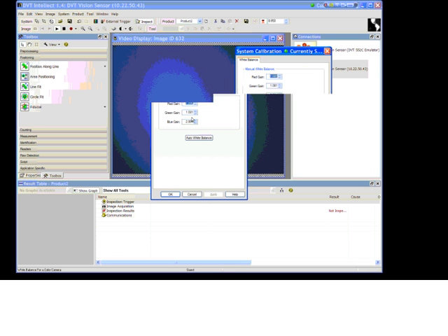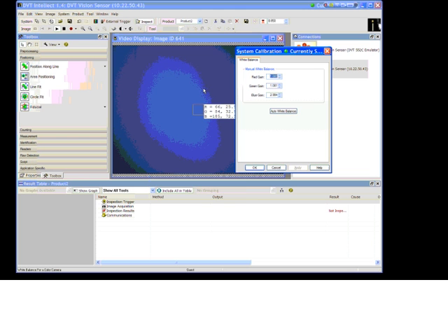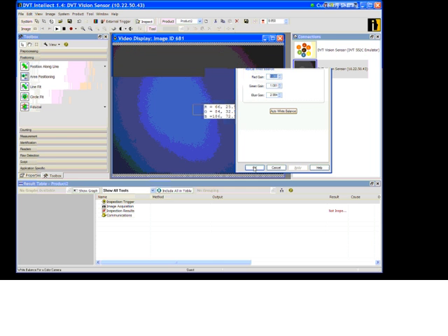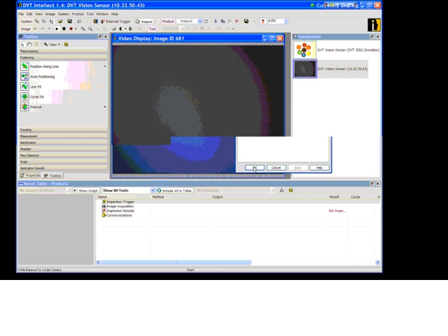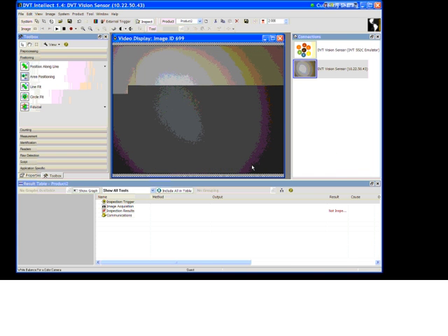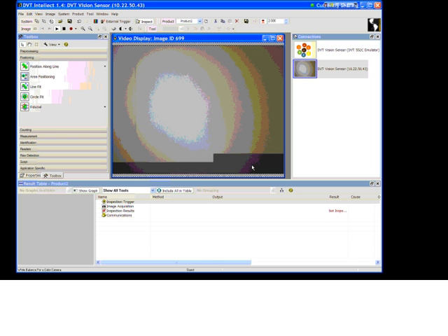Notice that it's very important that we have even illumination, not just because that is very important in terms of getting a good image, but also because the white balancing operation occurs in the center of the image. You can see that area right there. We press the auto white balance, and we see an image of a white piece of paper that is now kind of white. You'd see some changes because we don't have even illumination, and the gain was only adjusted in the middle, and now we have some ambient lighting.